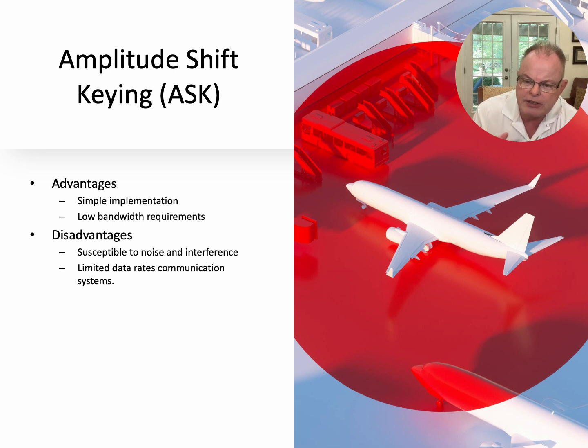The disadvantages are that it is susceptible to noise. So when you start dealing with noisy environments, if you've got things jittering up and down, that becomes a problem. At longer ranges, the signal decays and then it starts going down into the noise floor, which we've seen before. In the waterfall display, you can kind of see the noise. It fades down into there. And because it only has 2 levels associated with it, it does have limited data rates. So it kind of becomes a bit of an issue there.